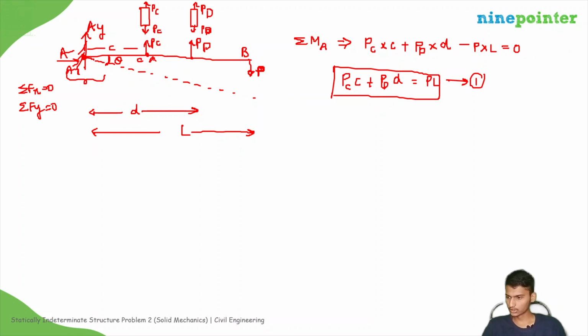So this is theta, then this will be the elongation of the rod at C. This will be the elongation of the rod at D. Okay. So this downward displacement, let us say dB. We won't write it as del B because you may get confused that it is also an elongation, but it is not elongation because there is no rod over here, right? So from this we can write del C by C equals del D by D, right?